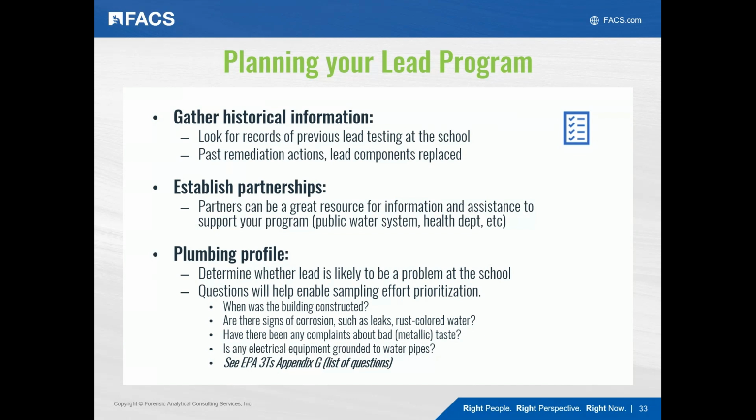And then this is an interesting one: is any electrical equipment grounded to water pipes? There's apparently a practice of grounding electrical equipment to water pipes. This is not good if there is any lead in the pipes, because the electric current actually accelerates lead corrosion. We actually worked with a school that had very high levels of lead in their drinking water, and they ultimately determined that it was related to this.